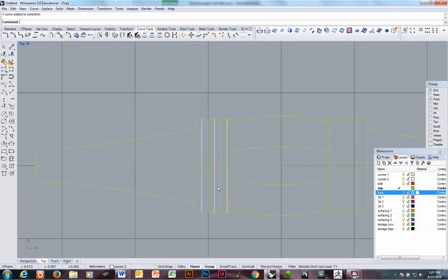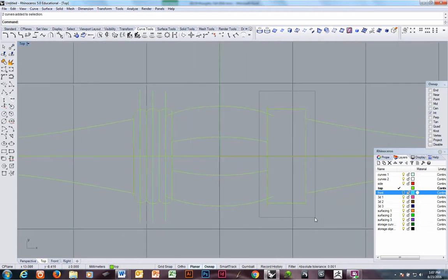And I'm going to also get rid of these lines. I'll do that by line, both sides, intersect, grab this. I'm going to pull it longer than the original lines. I want it clear that they're construction lines and that I can use them for doing intersections and things later. Throw these away. Pick up this whole assembly, mirror it over.